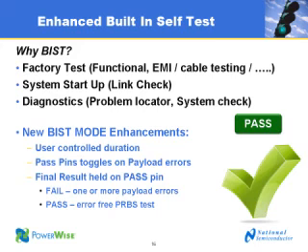So let's talk about another feature, which is the enhanced built-in self-test. We talked a bit about this in the last webinar, but the BIST is a very useful test that is used by designers and in manufacturing, particularly for the factory test, so functional EMI cable testing, the system startup as a link check, and also now for diagnostics, for looking for problems and system checks.